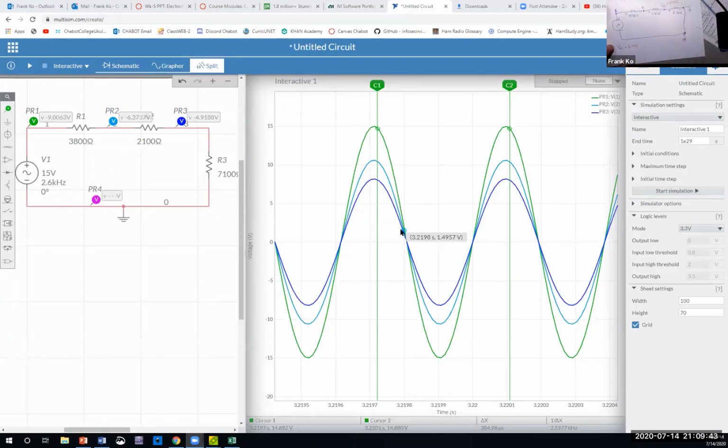Now, how about voltage at point B? The voltage at point B says that I have to have my red probe here. Where's my ground? Still over here. Do I have voltage between the red probe and the black probe? Clearly I do. And what I have between the two is the sum of the two. And the sum of these two worked out to be the 10.62.